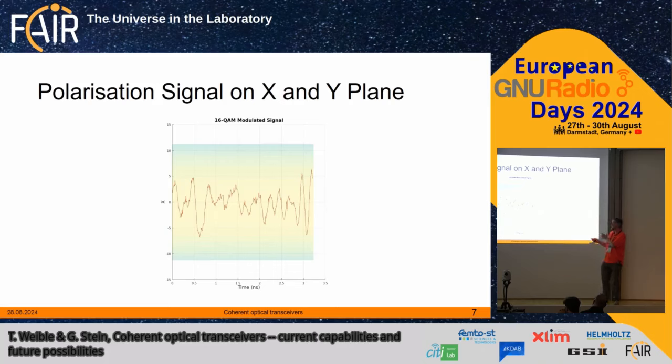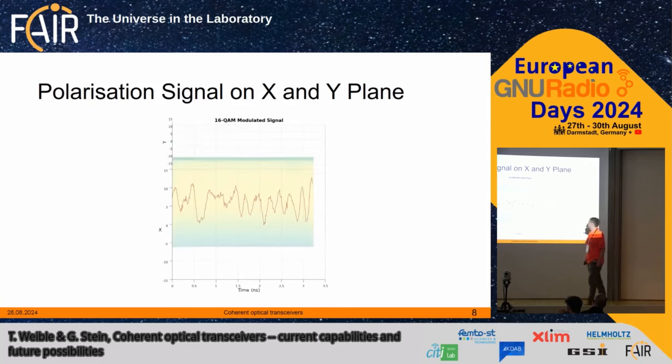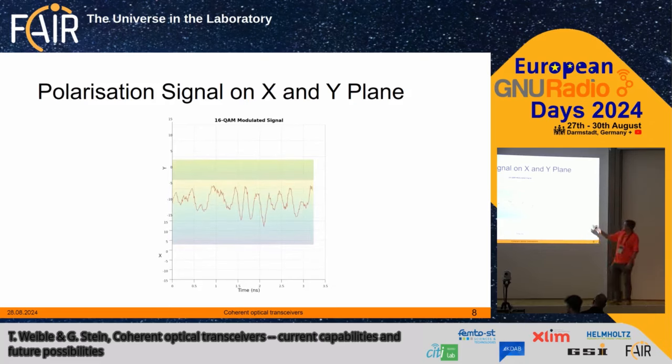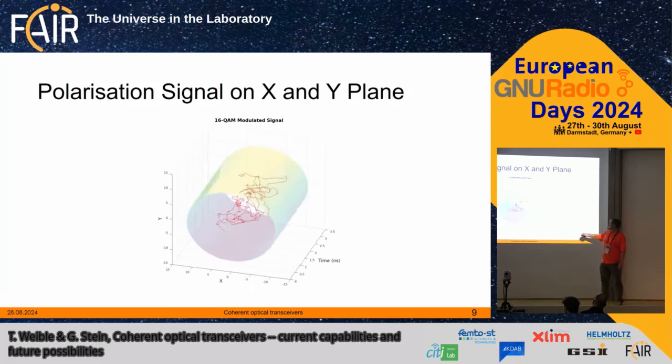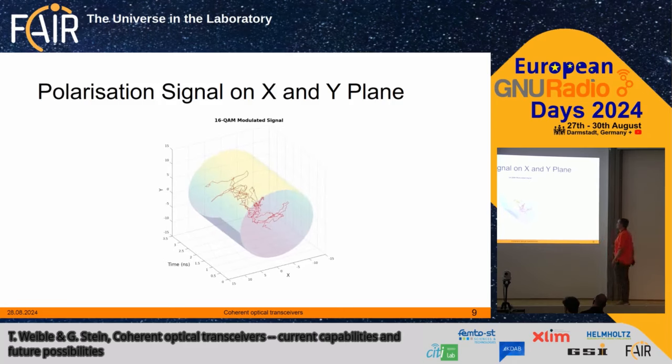So this is a signal you, through a simulation we calculated, you would get when you are checking current transceivers. Now if I rotate it even more, you see it becomes a little bit volumetric, and what you're really seeing here is the signal of a coherent transceiver. It transports a lot of information, and polarization has advantage. Since I'm talking about 2 planes we can benefit from. Of course, you are doubling the bandwidth already. So by just using polarization, you already doubled your bandwidth. Yeah? But that is one thing.